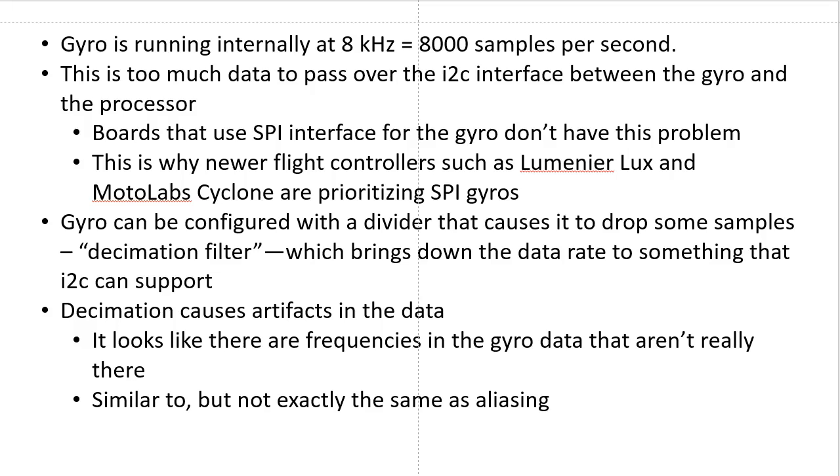You would have to finish everything you needed to do in under 125 microseconds in order to run at 8 kilohertz, right? With no overhead. So only the F4 boards can do that right now, and if you want to look into the RaceFlight project, that is a project that is working on implementing 8 kilohertz gyro sync on top of CleanFlight.